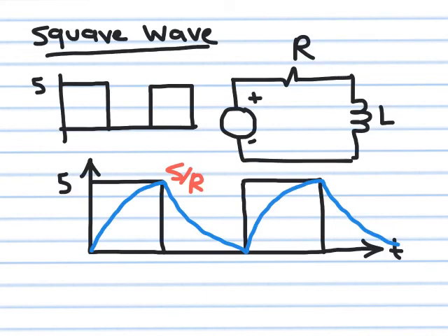What is happening to the inductor voltage here? In the beginning, you had no current in the inductor. Then VR is 0, so the whole 5 volts will appear across the inductor. So you start with 5.